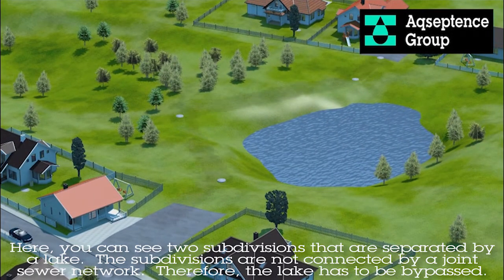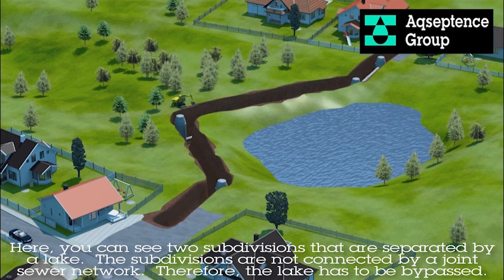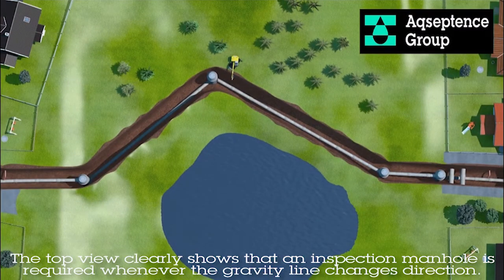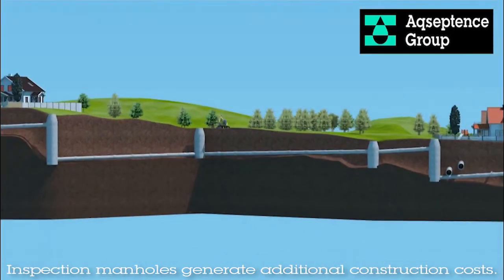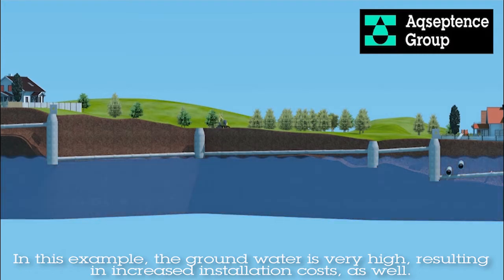Here you can see two subdivisions that are separated by a lake. The subdivisions are not connected by a joint sewer network, therefore the lake has to be bypassed. The top view clearly shows that an inspection manhole is required whenever the gravity line changes direction. Inspection manholes generate additional construction costs. In this example, the groundwater is very high, resulting in increased installation costs as well.